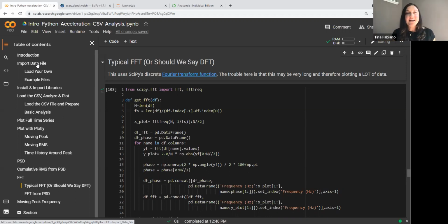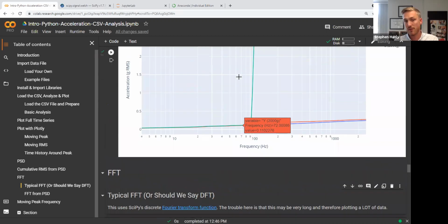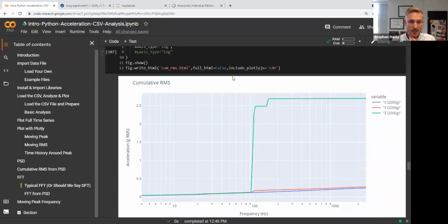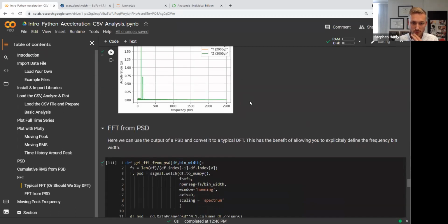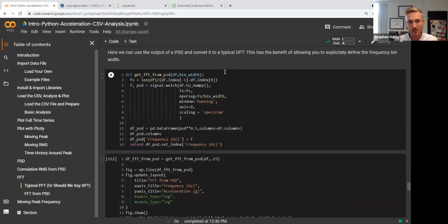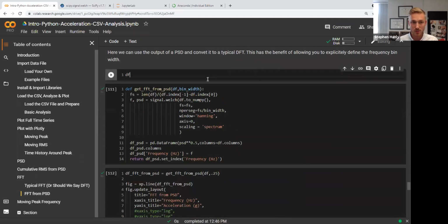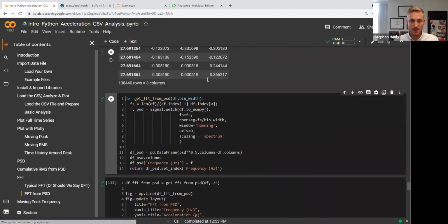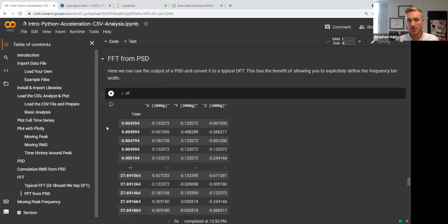And can we share any explanatory slides for PSD analysis of vibration data from a CSV file in Python? Yeah, we can look to do a very explicit deeper dive on that. You can follow along with this Colab link, and really, here is my function. My input was, if you remember, the acceleration data, X, Y, Z, and time.